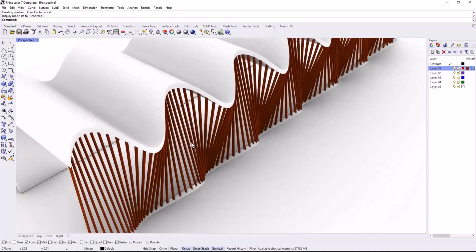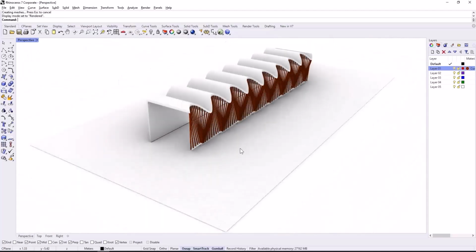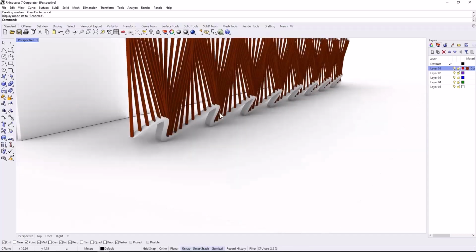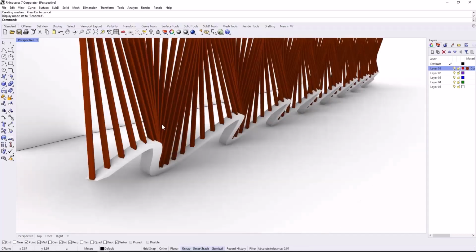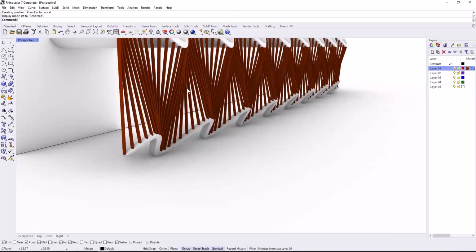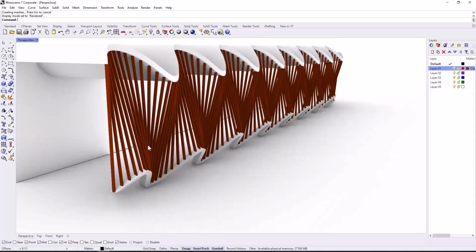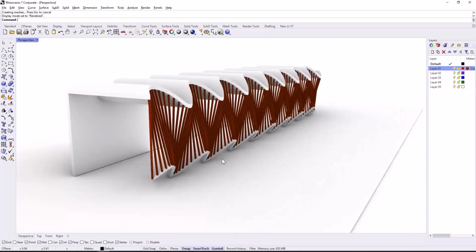So what should we call our final outcome? Parametric sinusoidal facade with alternating concave and convex curves can be a good name. You can increase or decrease the thickness of the lower section, and one of the key aspects of this modeling is the inversion of the sine wave amplitude, where the upper part has indentation and the lower part has protrusions. These points are systematically connected in pairs using a straight line.